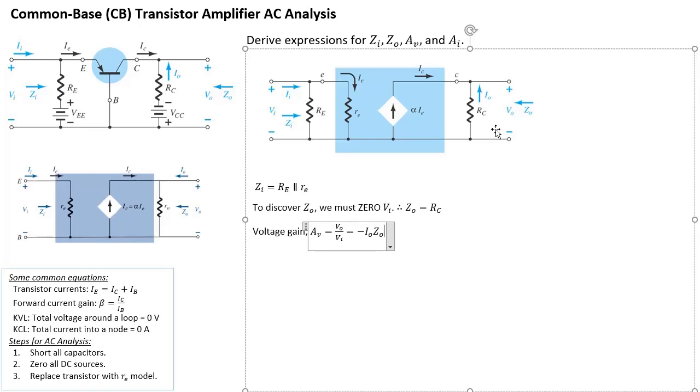All right. So that is going to be our VO divided by, so let me just put this in brackets, divided by VI. Well, what is VI? Well, VI, similarly, is just going to be II times ZI, right? So it's fairly straightforward. So that's what VO over VI is going to be. Okay. So we still need to figure out what IO is and what II is, because ZO and ZI we already have. So we just need to figure out what IO and II are.